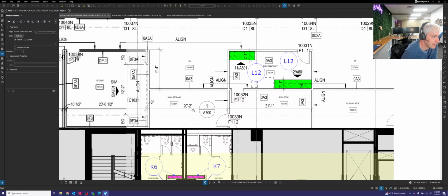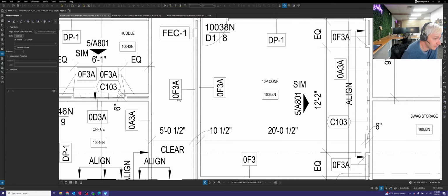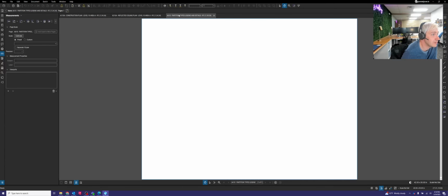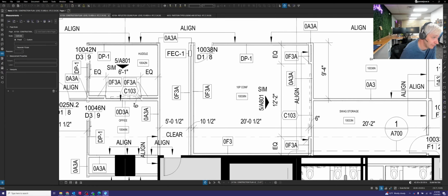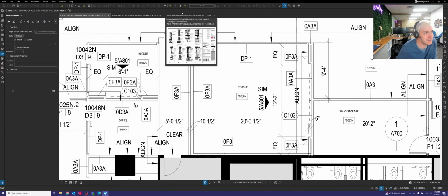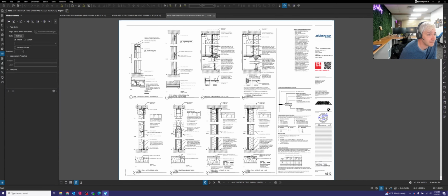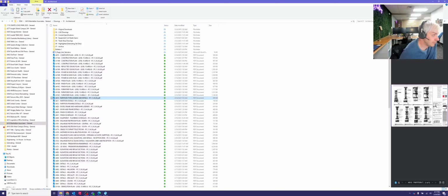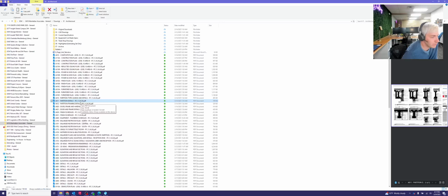As you make your way around a building, you will see that they do vary depending on where you're looking. So if you're trying to find out what a wall looks like, you do need to find the partition type legend to locate what that wall actually looks like. And this does a great deal of detailing that out for you. Anyway, not to get too off topic, let's keep moving.